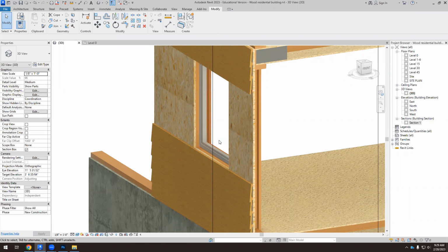I created this gap because I want to fix that element. This is a flashing, made of something metallic, so that if water comes here, we need this slope, and then the slope moves the water out. And that covers this part of the wall that I don't want to expose to the water or the wind. Okay, so I cover this part here.